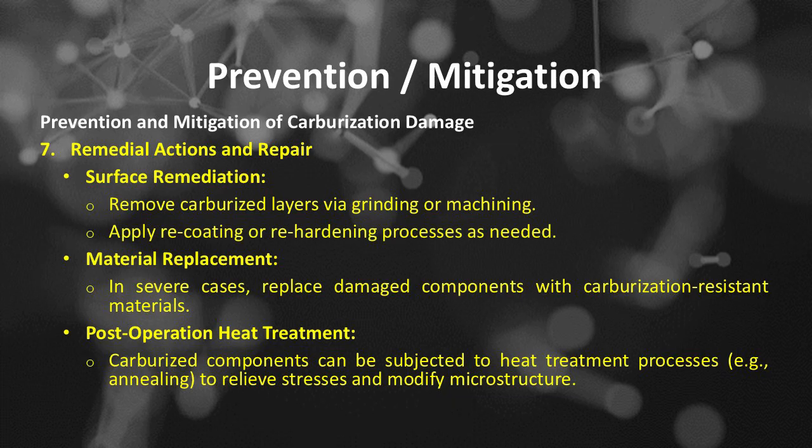The second of remedial actions and repair is material replacement. In severe cases, replace damaged components with carburization-resistant materials. And the third of remedial actions and repair is post-operation heat treatment. Carburized components can be subjected to heat treatment processes such as annealing to relieve stresses and modify microstructure.